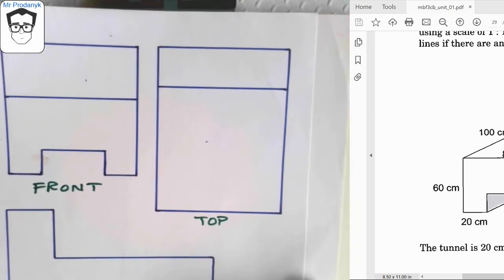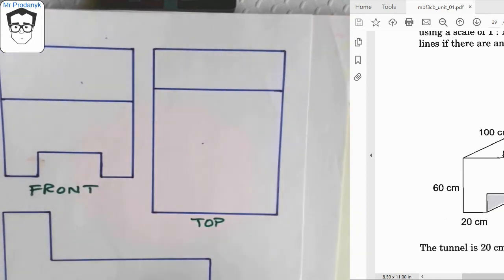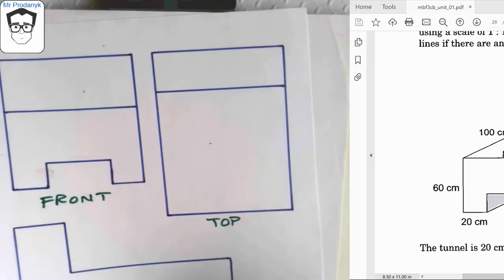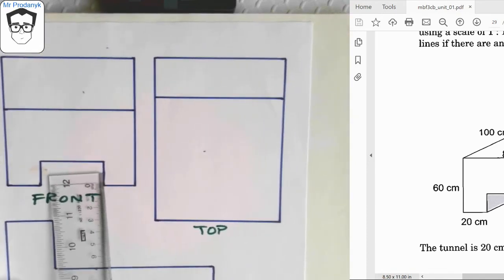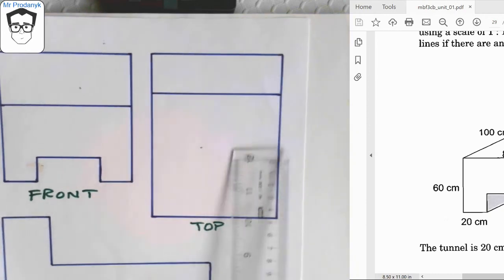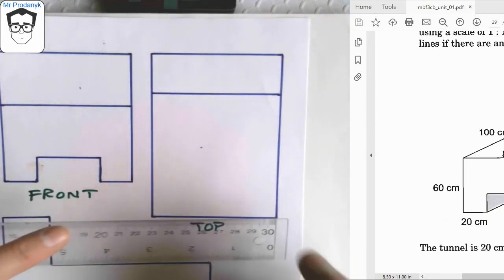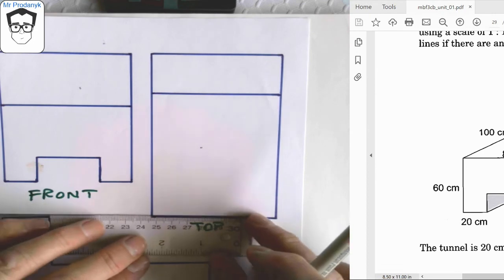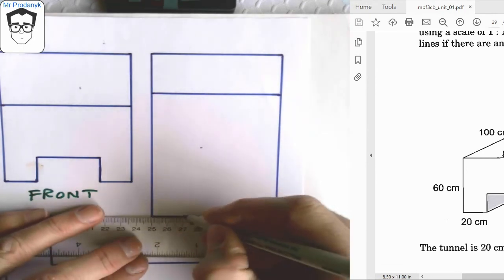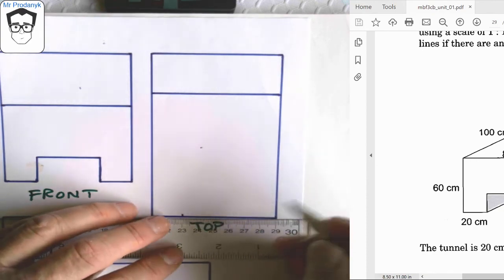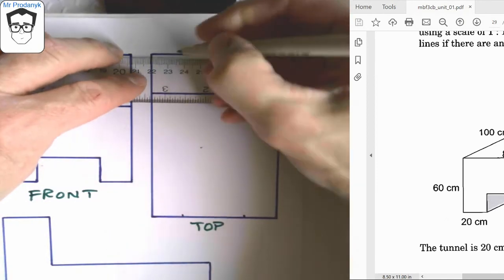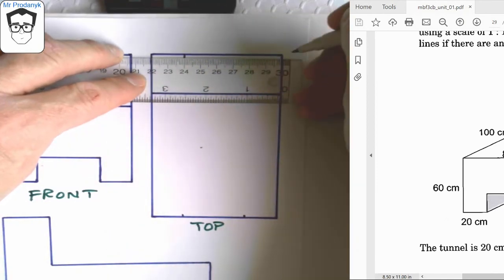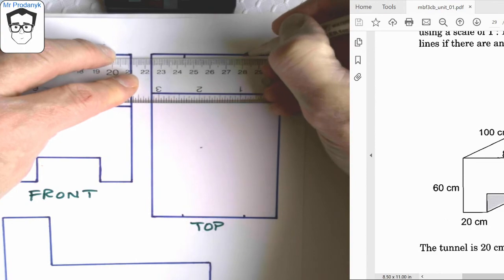But again, keeping in mind that this is some type of a clear crystal or clear plastic type of material, I would also see this channel down through the bottom, and the channel goes all the way through the bottom. It's 2 centimeters in on the drawing here, and it doesn't matter where I start on the ruler, it just needs to be 2 centimeters, so I'm just going like this right here, and then over here I'm going to go 2 centimeters, and at the other end I'm going to go 2 centimeters, and another 2 centimeters in from there.